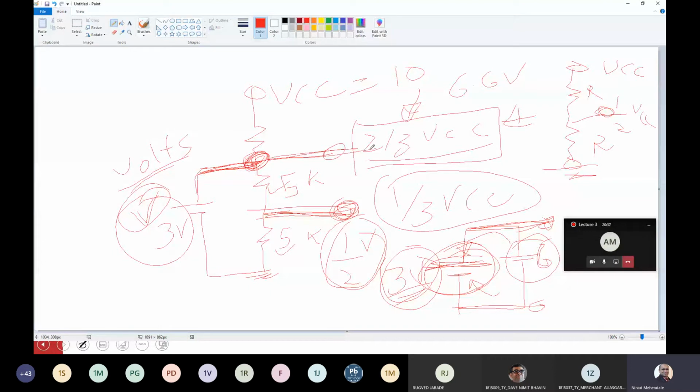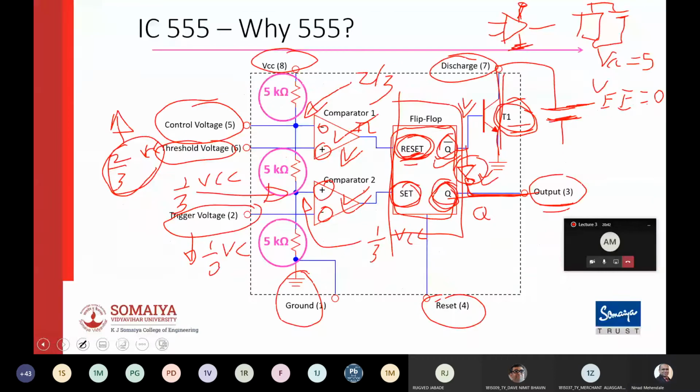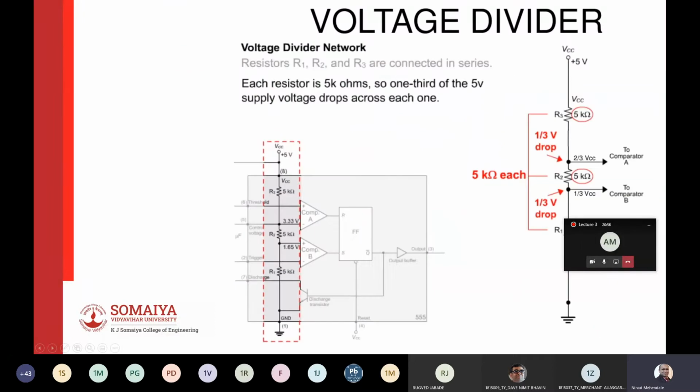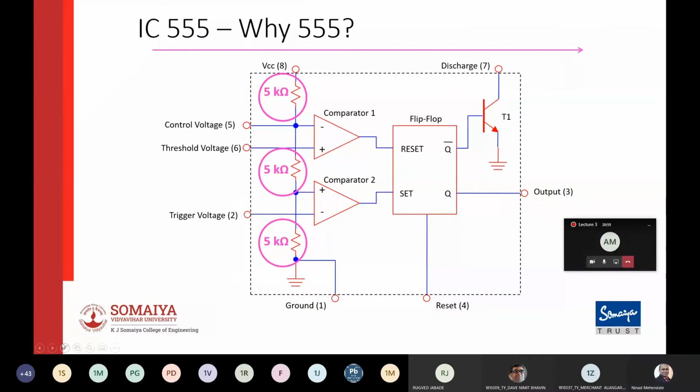and that's why now if you want to set the above flip flop, let me go back to the... I guess I can clear all the writings from this slide. Okay. So when I apply some control voltage at this pin, now this comparator can go high only if I cross this control voltage.